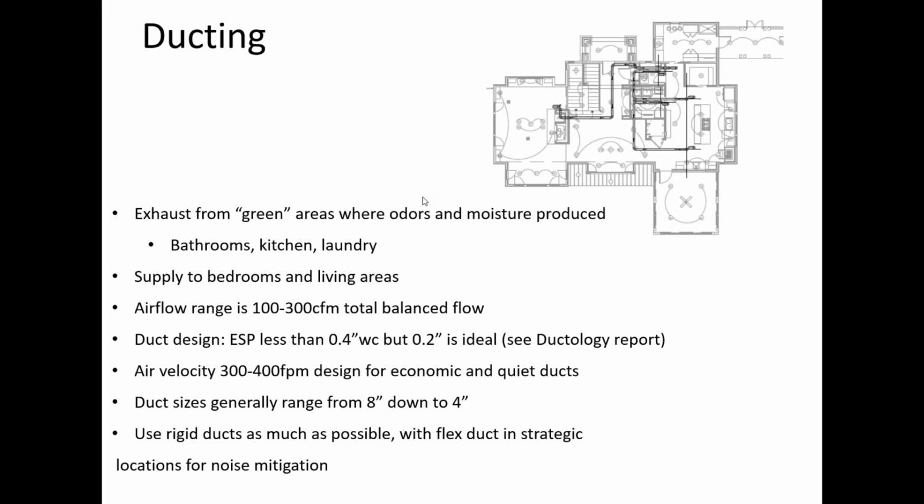Someone had asked then what the utility ducts are for. Those are actually not included in the CERV anymore. Those were for pulling from utility spaces, so like a heat pump water heater or a laundry space. But we've since removed those and just recommend adding conventional return back to the system like you would in other parts of the house.